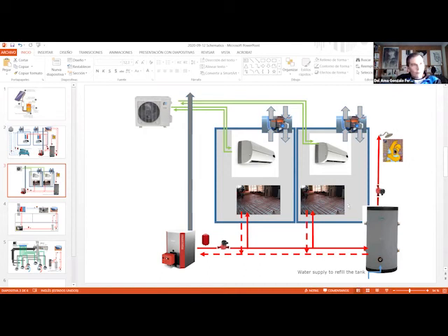It's more comfortable, it's more efficient, a radiant floor. I like it. But the radiant floor for cooling, it's difficult. So we need an extra cooling power. So that's why we have a heat pump with a split system. We need a heat recovery for ventilation, okay? Because here we need a mechanical ventilation. We don't have an air handling unit, so we need a heat recovery here.